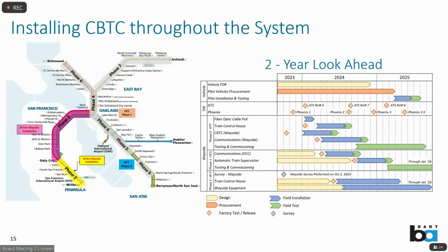This phase 2 represents the area where our most fragile and sensitive signaling system is. This outdated equipment is difficult to acquire and it has frequent faults. There is an urgency to replace this specific signaling system on the W line. The project has some strategies to accelerate completing phase 2, such as running what's called a captive fleet, which is a fleet that is CBTC converted and dedicated to run on the lines that go to SFO, instead of converting over all of the vehicles at once.